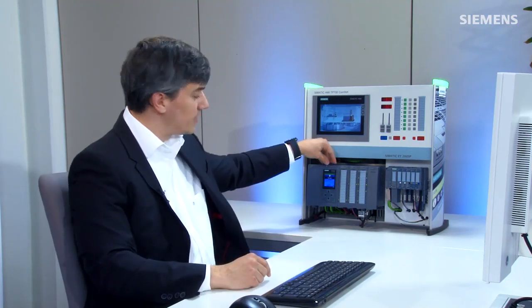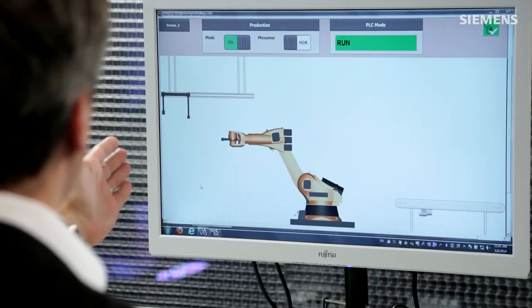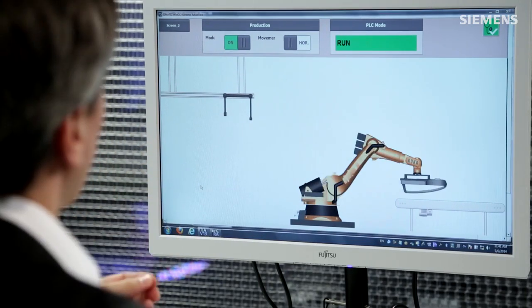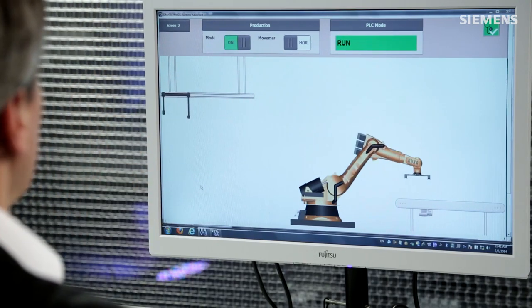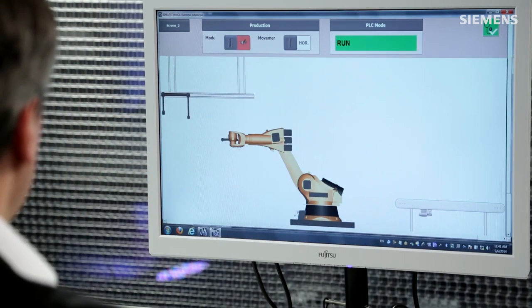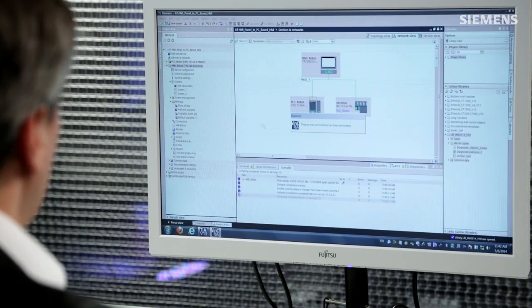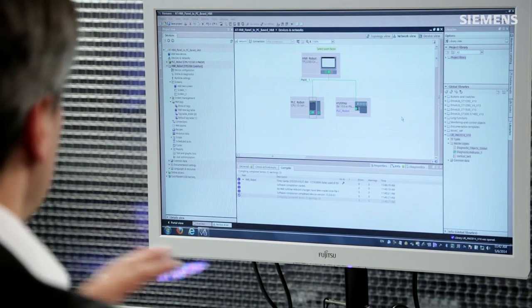As you can see here, I have a 1516 controller for this system and ET200 MP I/O, ET200 SP distributed I/O, both of which are on Profinet. If I come over here, I can see I'm virtualizing the 22-inch Comfort Panel for this particular system, and this is the HMI we want to replicate for the new plant expansion. What I like to do is actually turn off the system first. Let me shut down the runtime. And now that I have the project view, you can see the current hardware for this entire system.